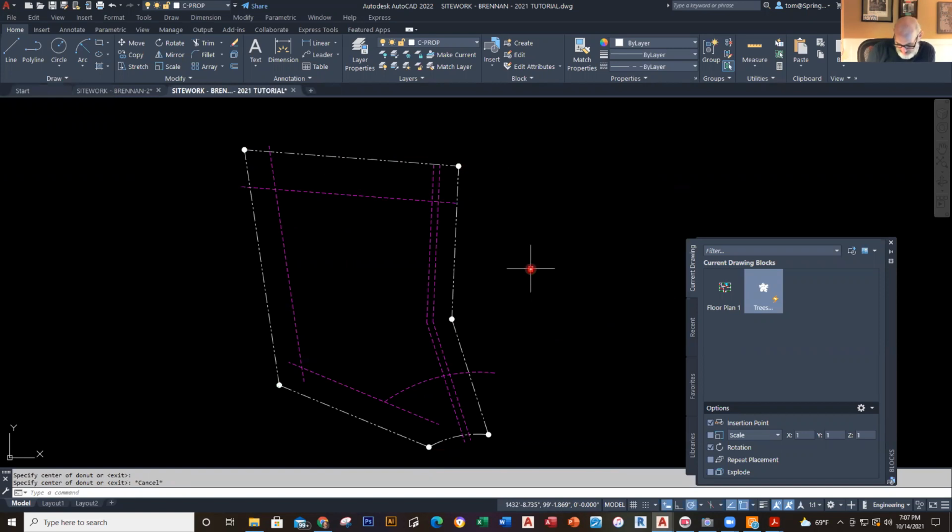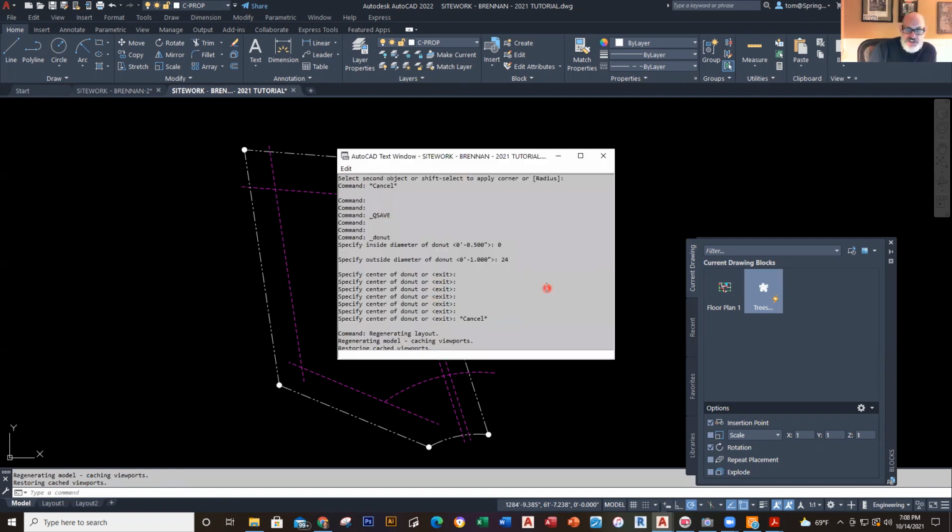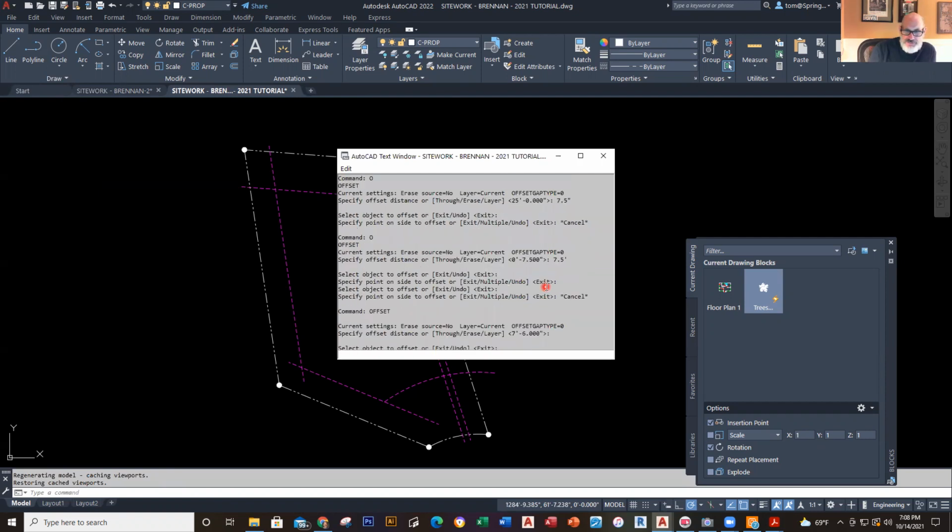And here, the next thing I'm going to do is I'm going to show how to actually put in the text. I already did this once before, but I'll go ahead and do it again. I'm going to show you a little trick here, so you don't have to go through and type in all these things again. You could just go to F2. When you go to F2, this actually allows us to go back and see what we typed in earlier.